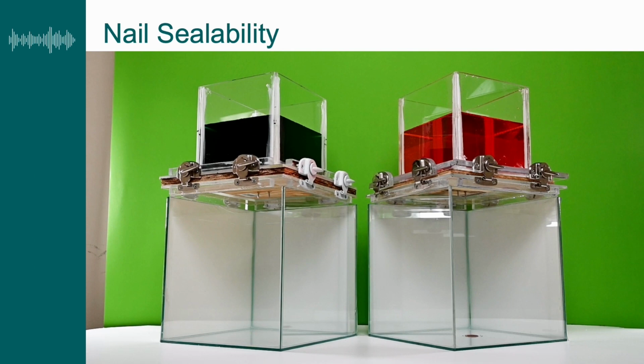And before 72 hours had passed, you could already see water saturating the deck, and at the 72-hour mark around there, water actually started dripping through the fastener head or through the nails into the chamber below. In real-life conditions, this would have caused, over time, property damage and mold growth. And on the other side, you see the polymer-modified self-adhered underlayment that even after days of exposure underwater, had no leaks.